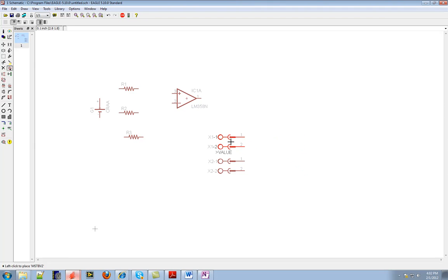So they each have two pins, so I only need 3, but I'm going to have to get 4 because I need 3. 1 is just going to be left hanging over. Okay, now I'm going to move these resistors so that 2 are vertical. That's my voltage divider. So I did the rotate tool.